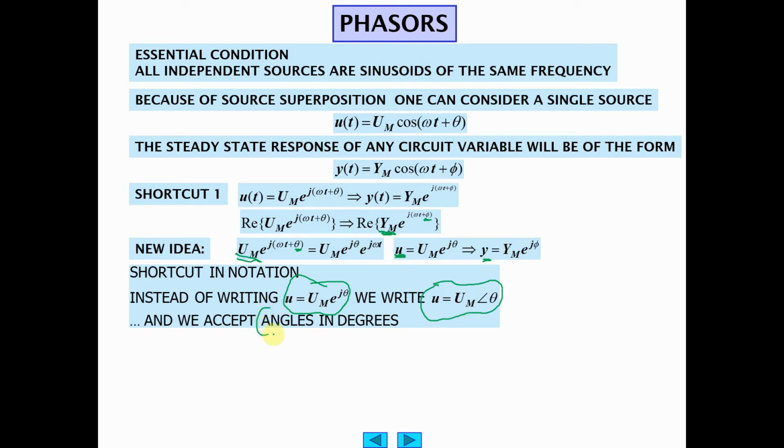What I said earlier about the angle in degrees versus radians, be careful about that. You can get fooled. So theta is often expressed in degrees, but when we're actually doing mathematical equations, or programming computers to do it, we need to remember omega t is in radians and convert from degrees to radians.